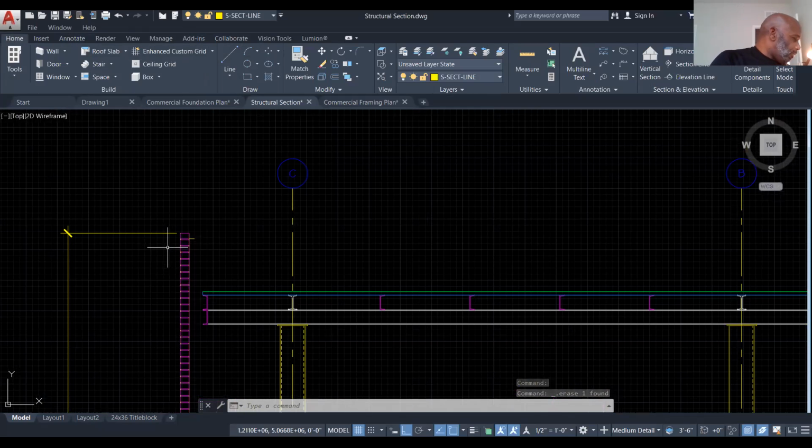So the insulation that we're using, we see that it is a 2-inch rigid insulation. I know some of you are familiar with fiberglass insulation that's probably insulating the walls of your home or your ceiling, and that's called fiberglass batt insulation. But commercially, that's not used too often. They use rigid insulation, which is like a foam material in essence.